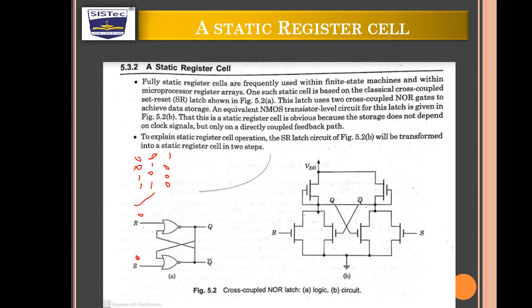This is the equivalent circuit of the NOR latch, the cross-coupled NOR latch, and this is a static register cell, obviously because the storage doesn't depend on a clock signal but only on a directly coupled feedback path.